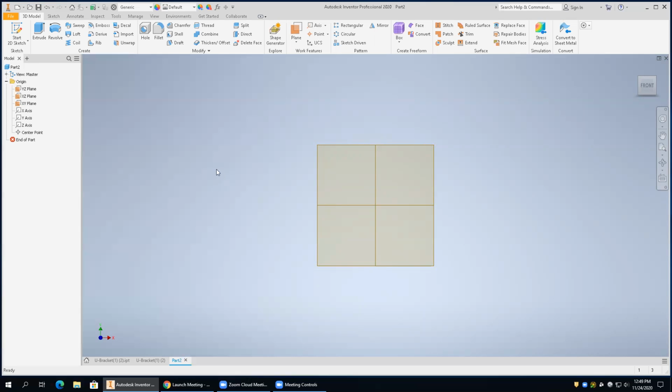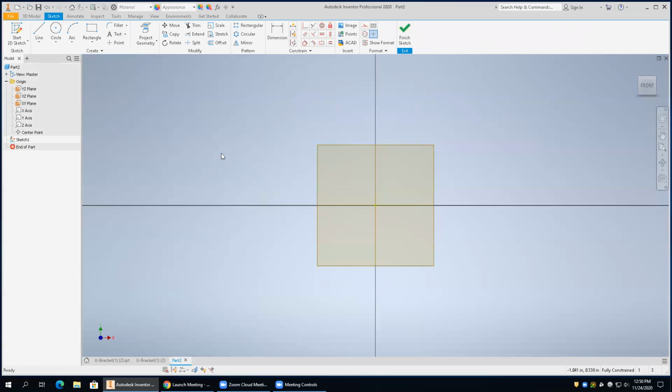So we're going to generate a pulley that has kind of an edge at the top, and it's got a thing in the middle. And we're going to revolve it about an axis. So you've got to watch what I'm doing here. This is kind of weird, but it works really well. So we're going to generate a sketch. We're going to go to sketch, and we're going to tell it what plane we want to start in. You can come over here and pick them, but I can also just pick over here. So I'm going to tell it I want to start in the XY plane. So it should look like that.